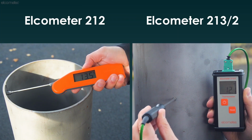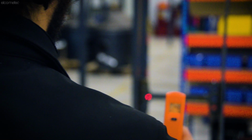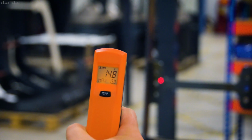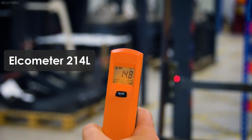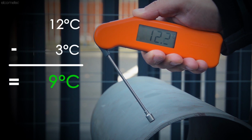a digital thermometer with a surface temperature probe, such as the Elcometer 212 or 213, or an IR digital laser thermometer for measuring substrates that are on a moving production line or at extremely high temperatures, such as the Elcometer 214. Once you have your surface temperature, subtract your dew point temperature from it, and you have the delta T.